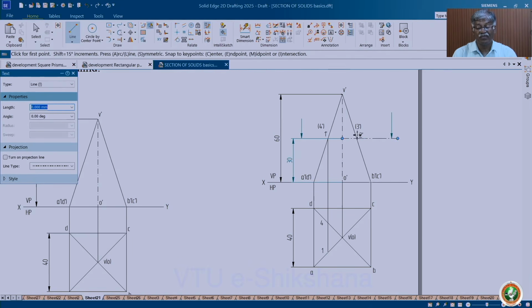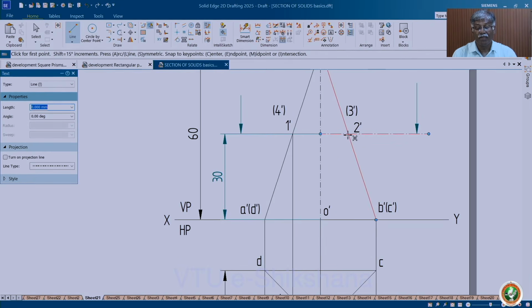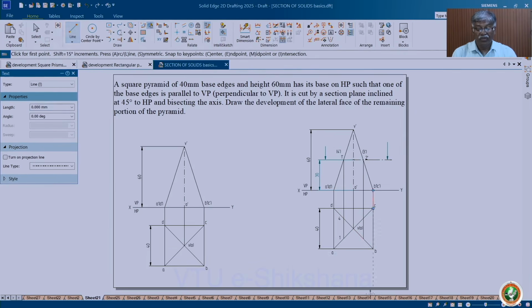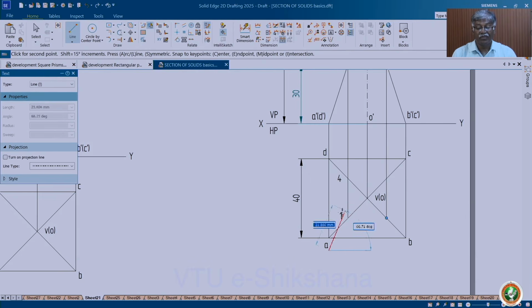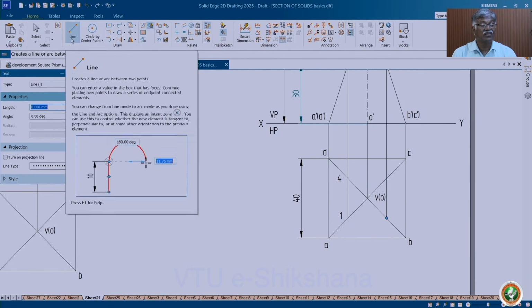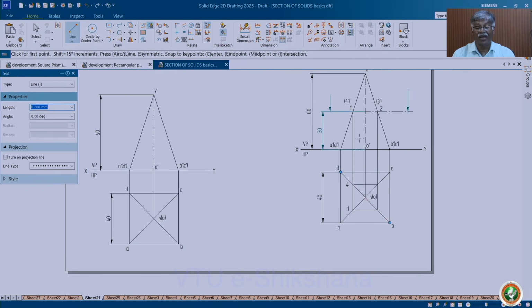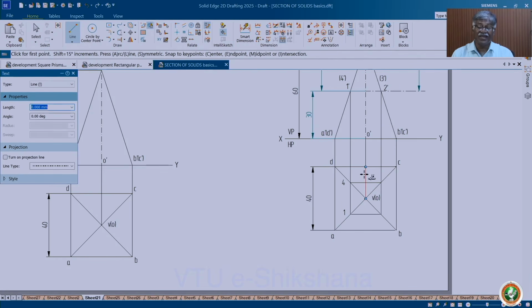Project 2 and 3 intersection, bring it down vertically, see that point is there. Now, you see that this particular item is for section. Join 4 and this point, definitely you must get horizontal here also. This particular item is called section. So, parallel to the base, definitely this itself is true shape. Okay. So, what exactly sectional view I will tell you.